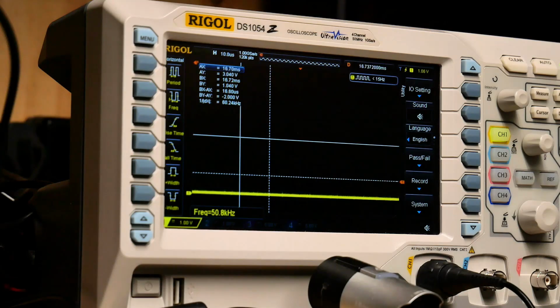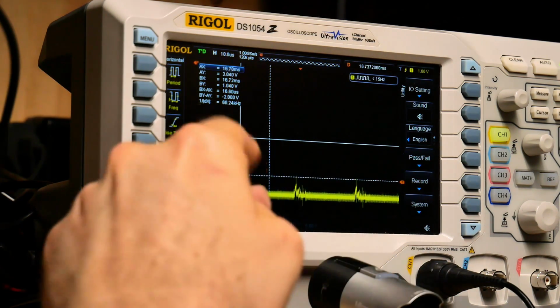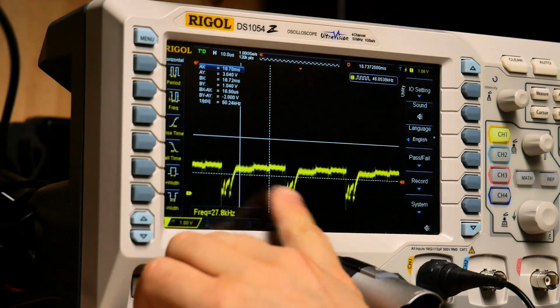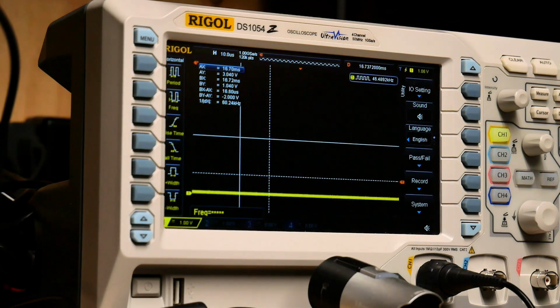And if I turn the computer off and on, oh, you do get a quick pulse of 5 volts actually. Interesting. So briefly you see 5 volts. And then it gets stuck low. And this one, same thing. So on the left chip, all these ones that are stuck low have a brief high pulse and then they drop. Right to the right chip, this does not look right. Let's turn it off and on.